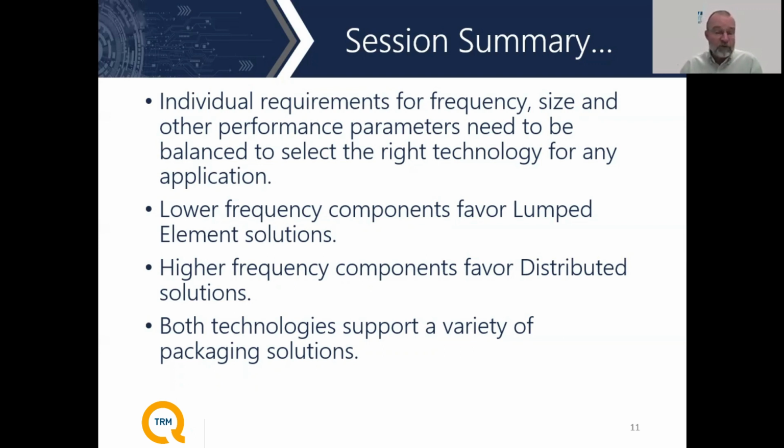Sometimes there's a printed transformer that will give us lower insertion loss in that frequency band. But we want the better isolation, for example, of using a transformer for the output for the divider for the two-way. So there are a lot of things that TRM does with mixing technologies between printed or distributed technologies and lumped element technologies to sometimes get the best of both worlds.